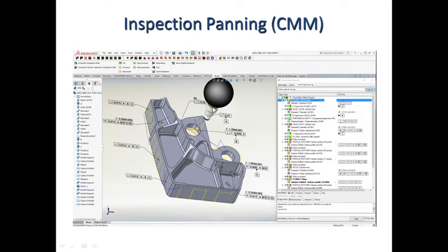There is a touch probe available in the CMM machine, which is going to touch the various points on this part. Wherever the probe touches the part, it will gather the coordinates, that means the x y z coordinate of that point. Similarly, wherever you want this probe to go and find out the coordinates, it can gather that information, and based on that information it can inspect. Basically, inspection is comparison of this produced part with respect to its CAD model